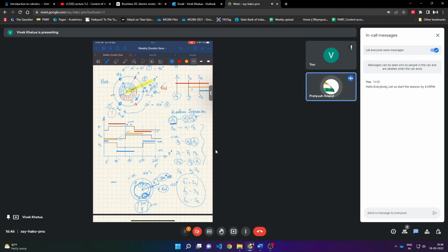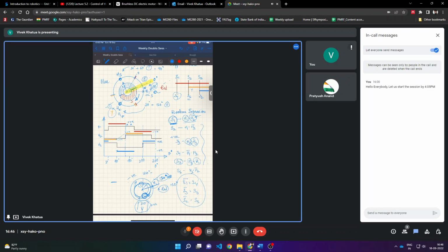Hall sensors will also be increased again? You can increase the number of hall sensors, but they are not going to give you any switching diagram that will be different. It will only give you position accuracy. When you want a smaller motor, which is BLDC, you cannot put more than 3.